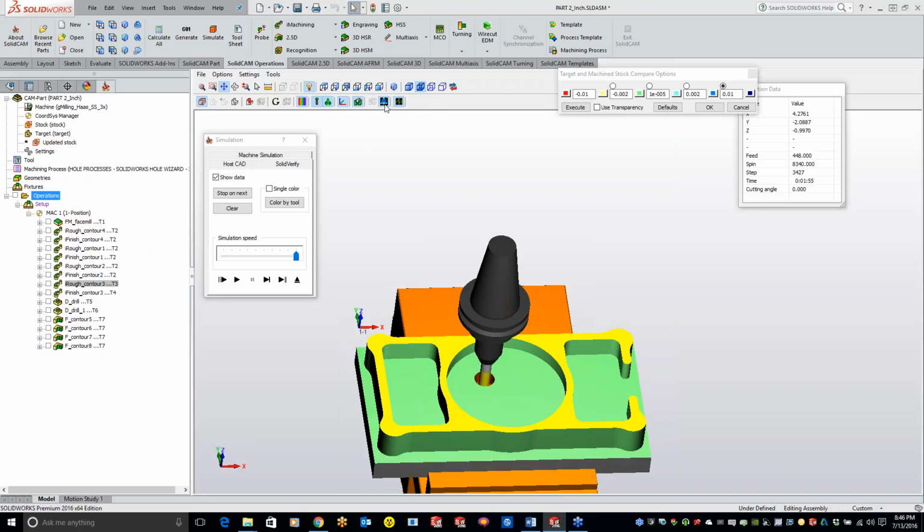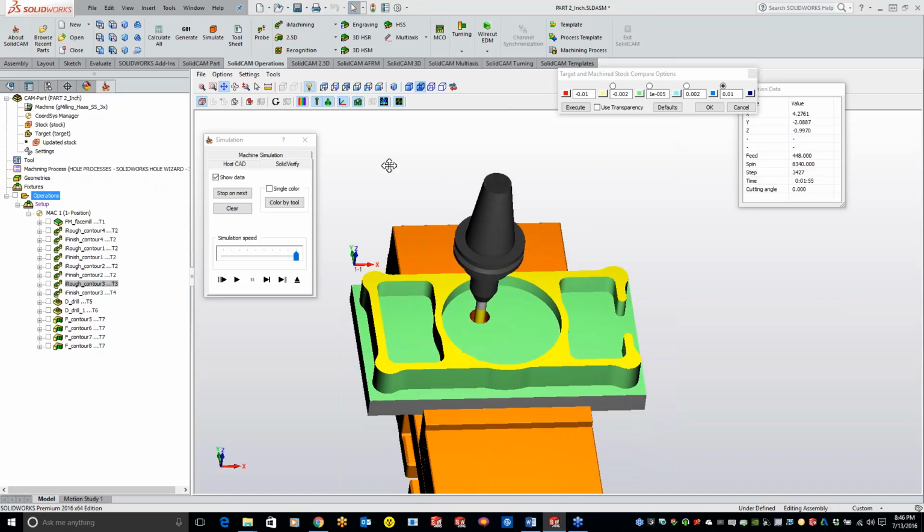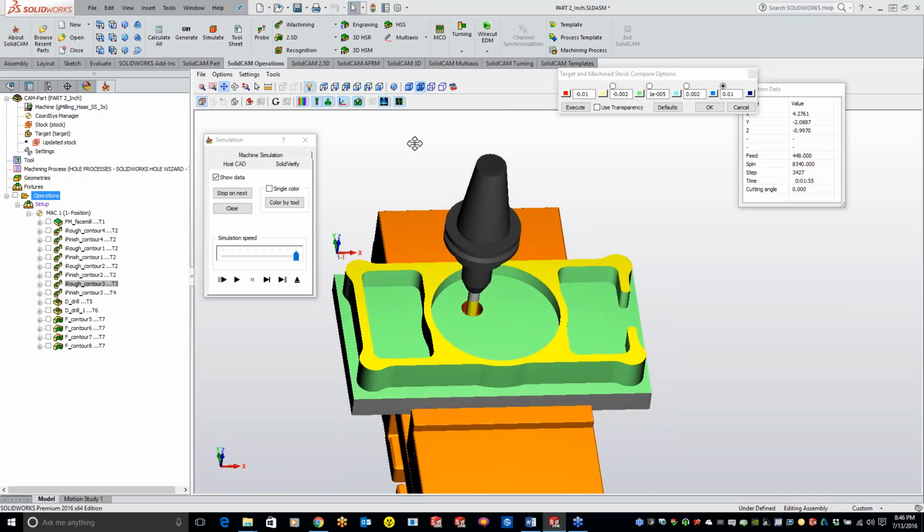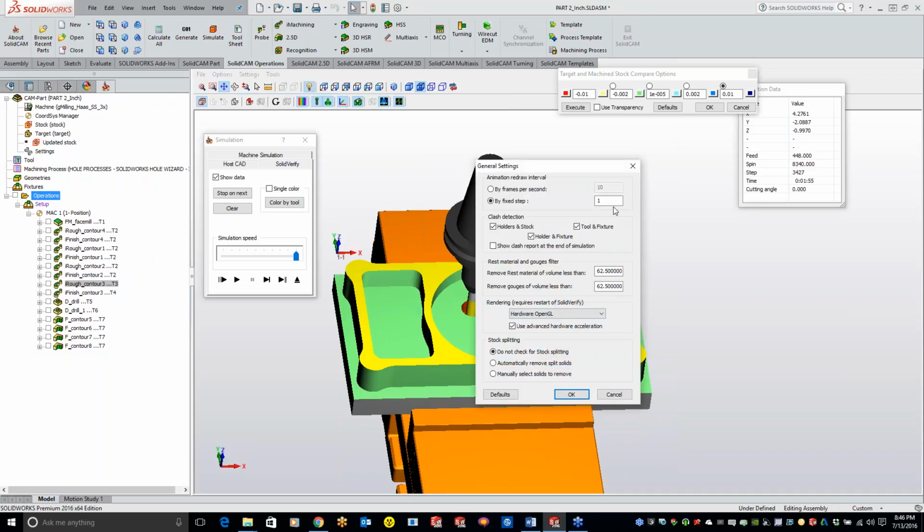Like I said, you always want to have the rocket ship turned on. Always want to have the multi-core support on there for you guys. In the tool, the self-intersect, I've never used it before, so I can't really give you guys a lot of insight into what's going on there. But the most that you're going to use is your accuracy and your general. Like I said, you can do a redraw to show every single step or every 1,000 steps, and it will speed up your verification.